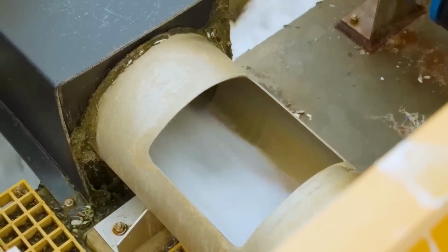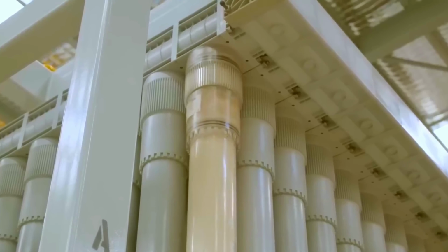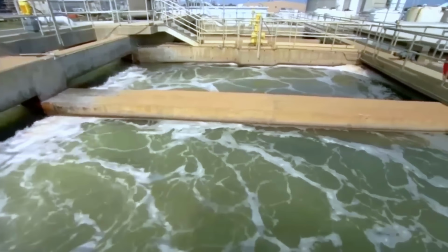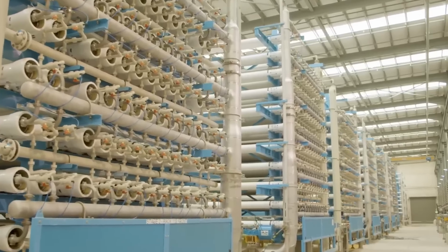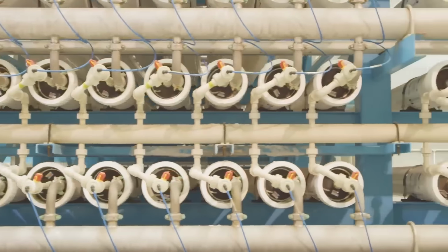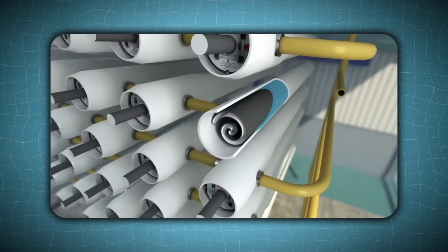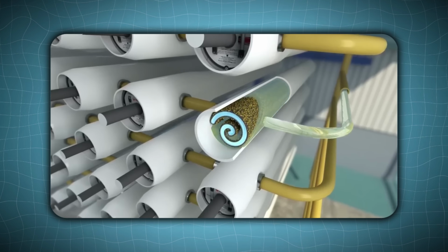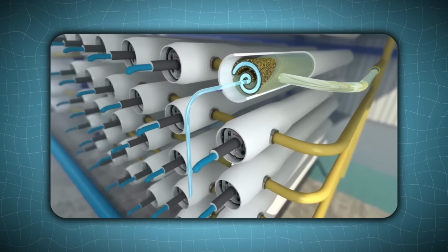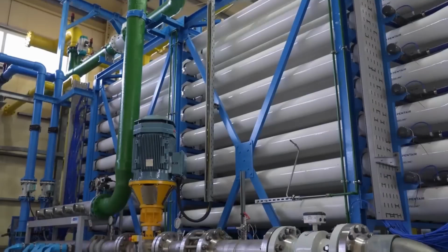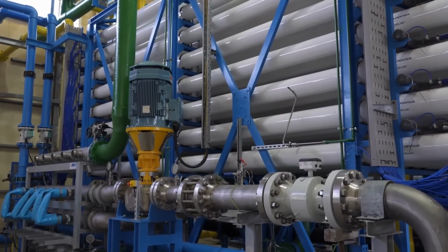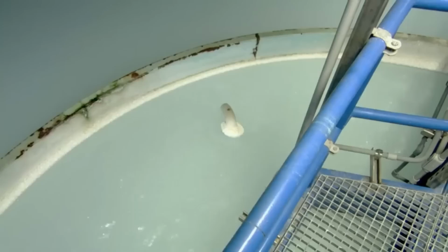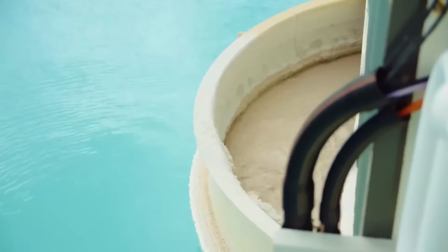Trying to recover much more water makes the process increasingly difficult. As fresh water leaves through the membranes, the remaining stream becomes saltier. Higher salinity means higher osmotic pressure, greater risk of mineral scaling, and more energy needed to continue forcing water through the membrane. Large desalination plants divide the flow across thousands of membrane elements arranged inside many pressure vessels. This modular design allows enormous volumes of seawater to be processed continuously, while sensors monitor pressure, flow, and water quality across different sections of the system.